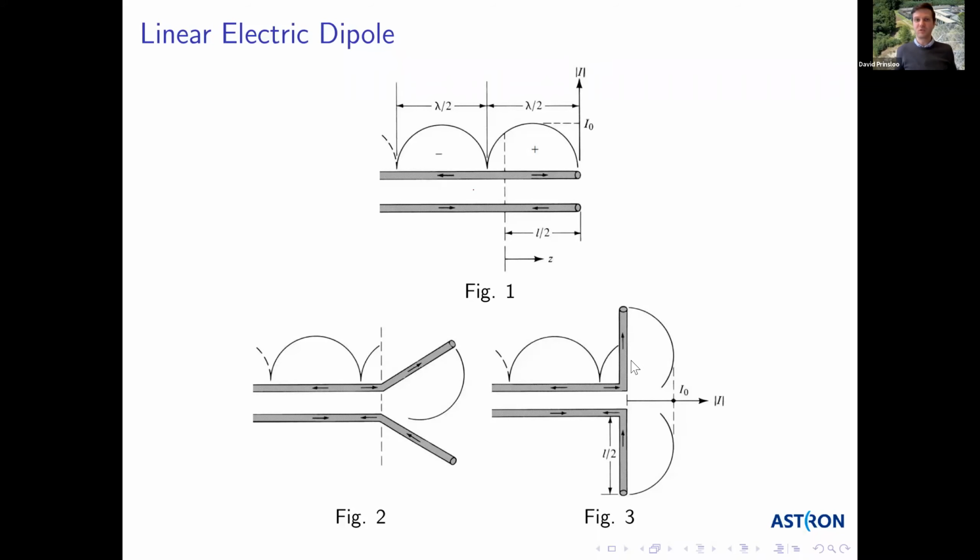And that's the point that I want to get to next. I hope you can see from this representation that this standing wave is a maximum at a quarter wavelength from the open circuit. So if you were to bend this dipole open at a quarter wavelength distance, you have a result of half a wavelength. And at that point, the current is a maximum in the center.